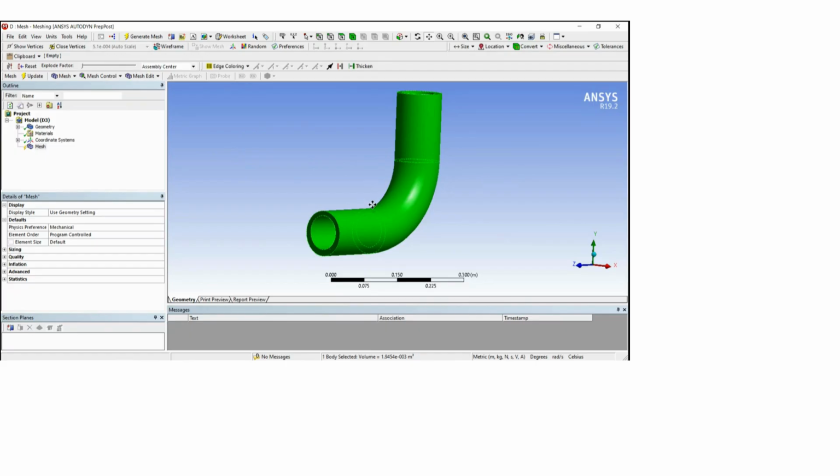As you all know, the hexahedral cell is one of the very useful cell elements because it gives a lower cell count when we generate the mesh on a complete body. It gives a lower cell count as compared to tetrahedral, and it makes a structured mesh. Structured mesh means elements will come in one row. Once we do a calculation in Fluent, the calculation on each cell consumes less time. That's why we have already heard that structured mesh is always good in CFD.